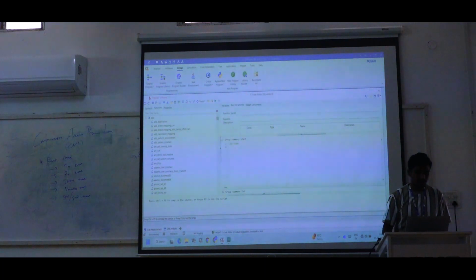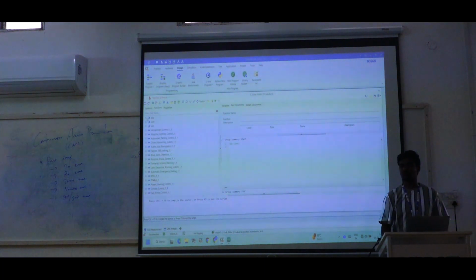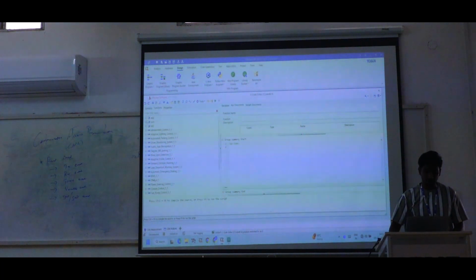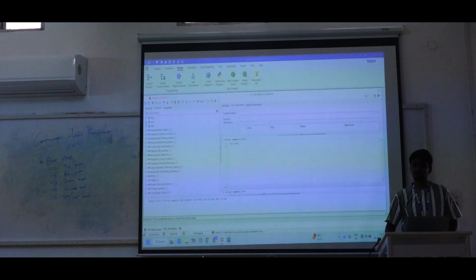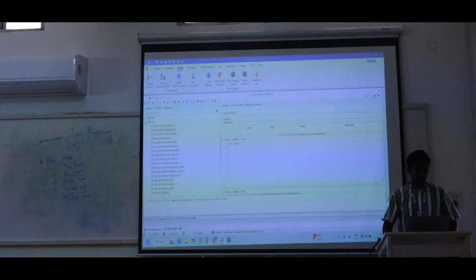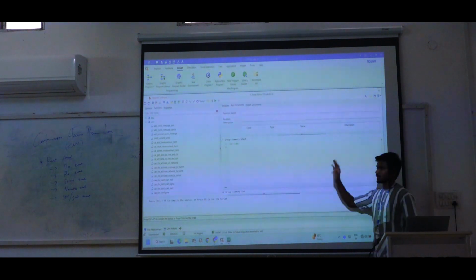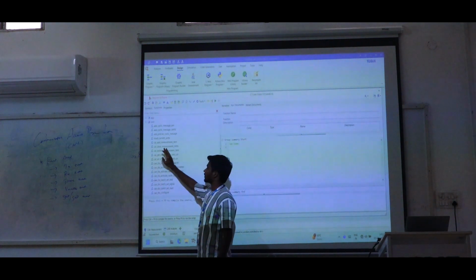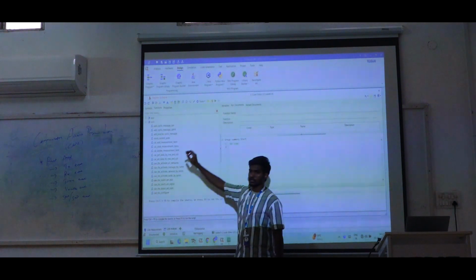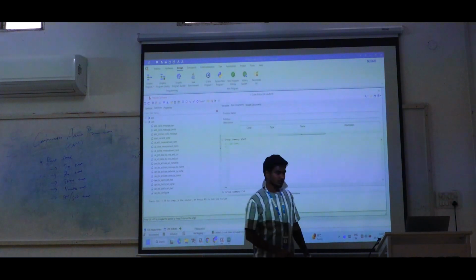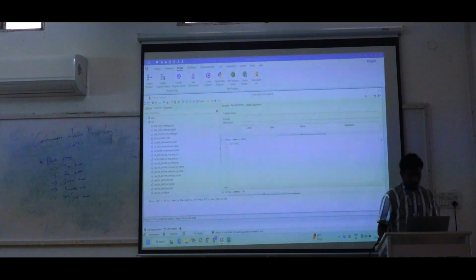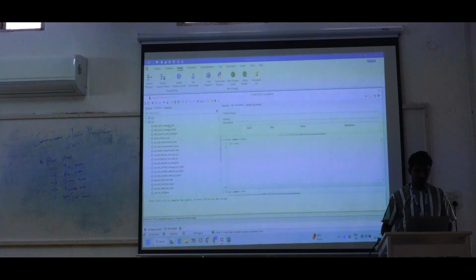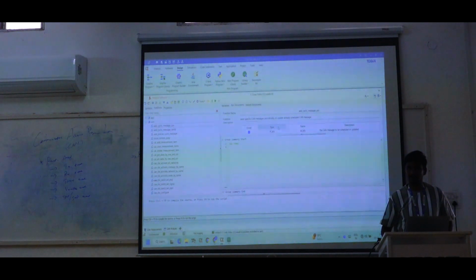CAPL is a Communication Access Programming Language. So you just drop down and then go for COM. COM means communication. These are common functions now in the entire CAPL scripting. So just drop down on the COM. For example, the first one has add cyclic message CAN. You just click this on the right side and it opens the API documents.